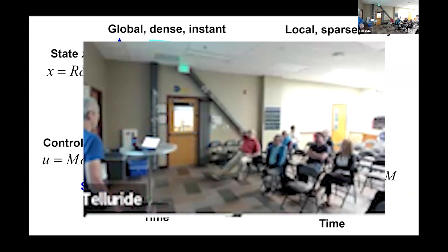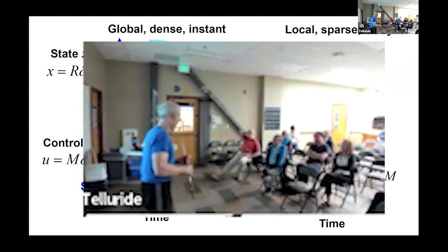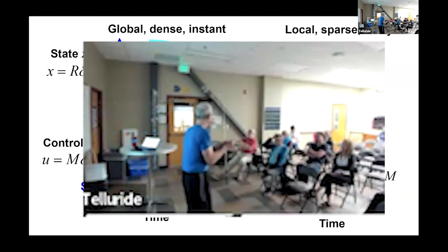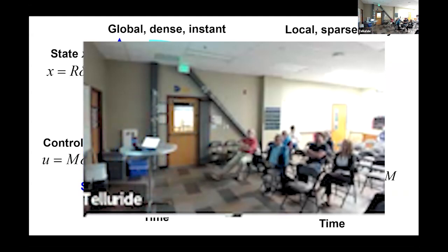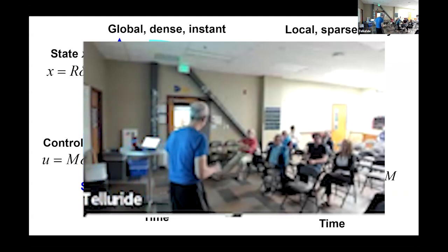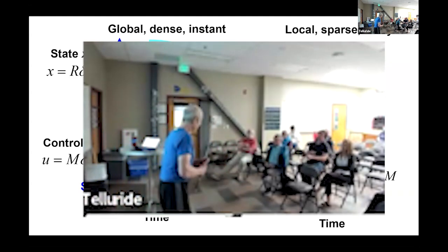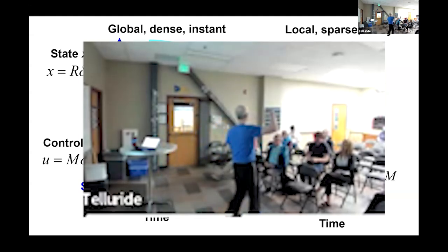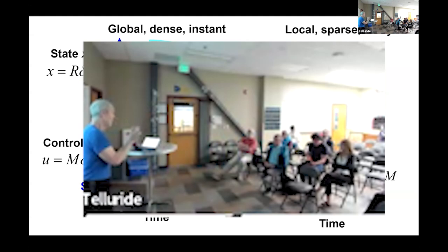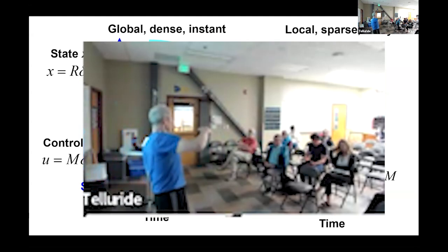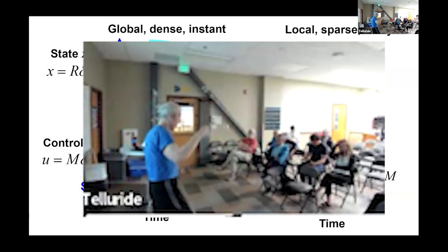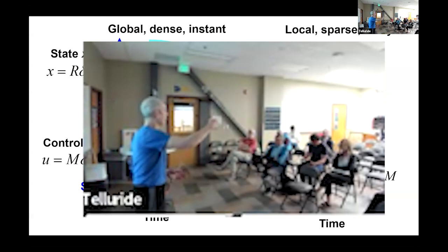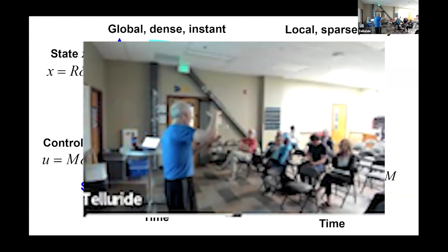That would be a situation where not only can I act only at certain points in space, but I can only act every once in a while in time. That's still a convex optimization problem. No problem, I can do that. And so you can certainly imagine having a multi-rate system, where I can act really quickly, but my neighbor only acts every once in a while. And then you're going to want to do that across layers. That's the part I would say is a weakness of this, because if you have two layers doing this, running MPC, the lower one is running MPC on very small things, and the higher one is on slower timescales running a longer MPC. We have a paper on this, but we're not solving the